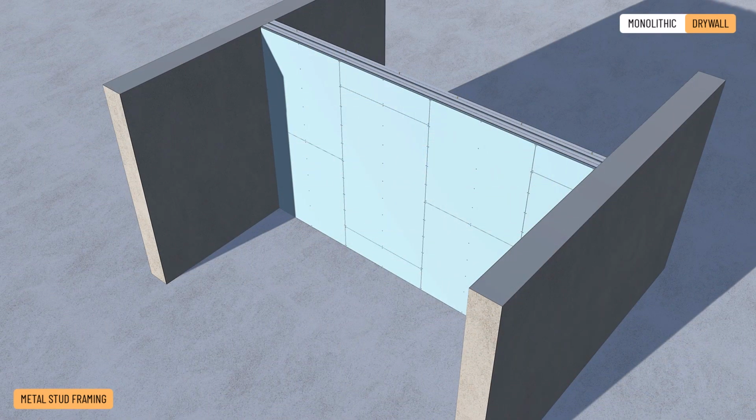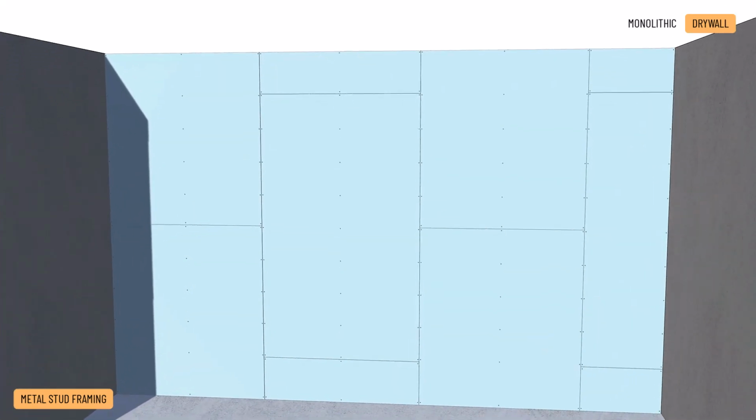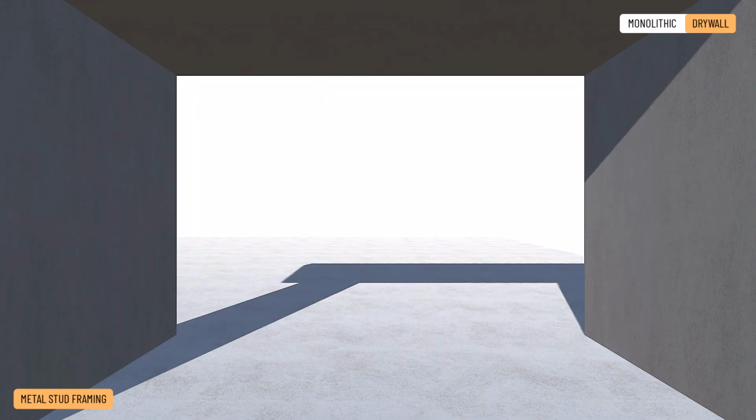In this example, we use these elements to build a double metal-framed plasterboard wall with increased sound insulation and fire protection. 1. Construct the metal stud framing partition wall after plastering is completed. We start building the stud framing directly on the screed. 2. During the setting out process, we mark the lines of the walls on the structure, the position of the openings and the connections.